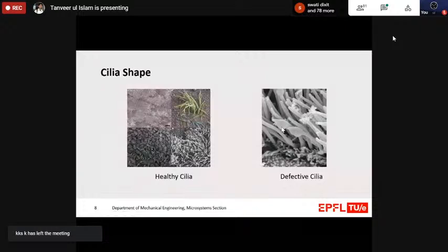As was said in the introduction, I'm trying to study what the effect of these defective cilia will be in our body. Now why is this important for us as engineers? We see, like the example of the embryonic node, that although it's a bioprocess, if we artificially reverse the direction of flow, a lot of changes happen in the rest of the process that follows. So from a bioprocess, it becomes a fluid mechanics process, because it is simply the flow that decides whether the organs will be placed in the right configuration or not.